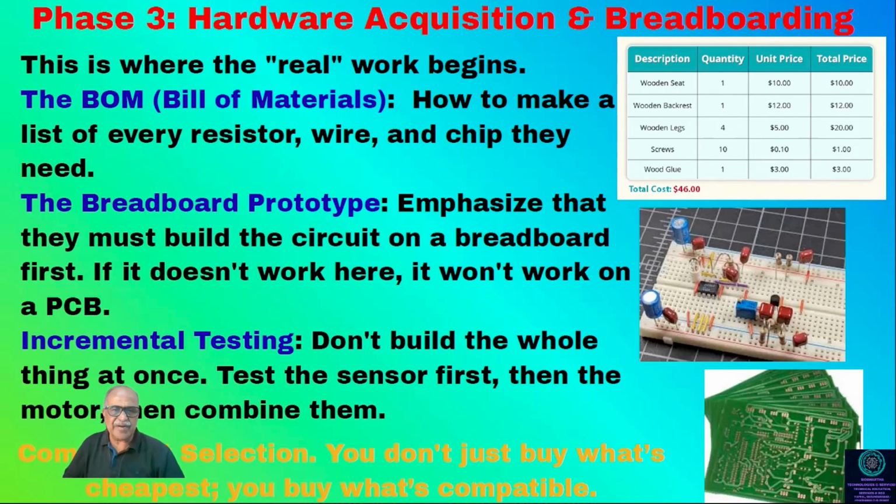Now, the second part is breadboard prototyping. Emphasize that you must build the circuit on a breadboard first. Please remember, if it doesn't work there, it will not work on the PCB. If it works here, then only can you transfer your components properly onto the PCB. So that's why breadboards are important.